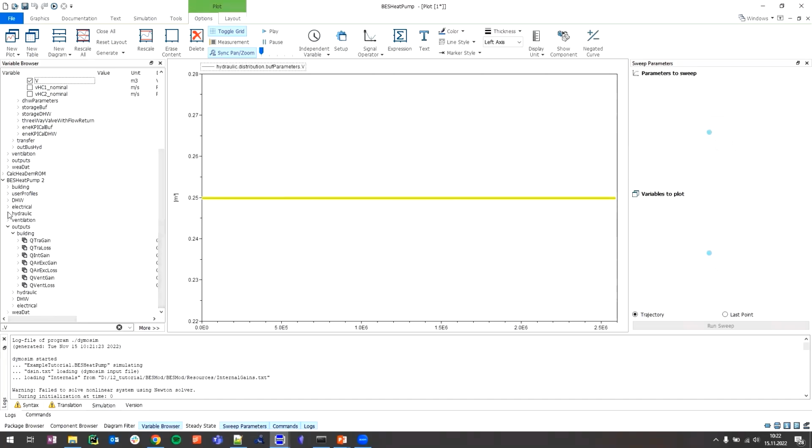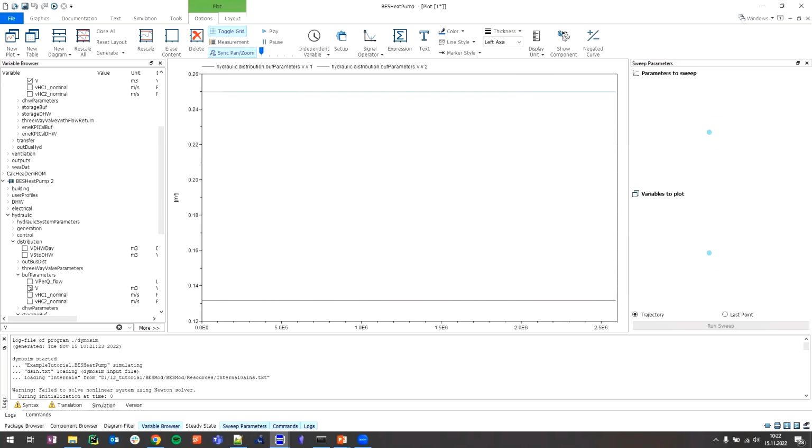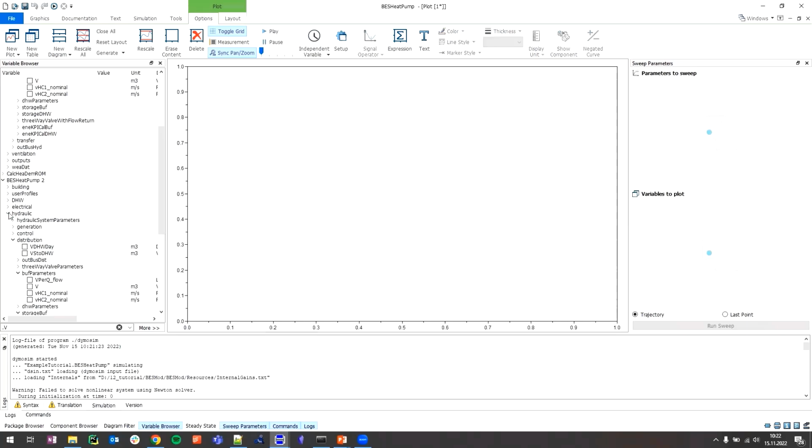And down here we have a little bit less, so only 130 liters, because we roughly have half of the demand, so we don't need that much inertia. So all of this is changed according to norm. So every time you change the heat load, you will have basically different design of the energy system.